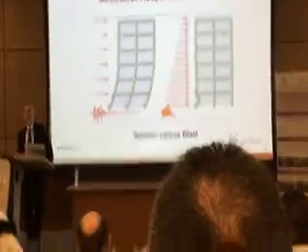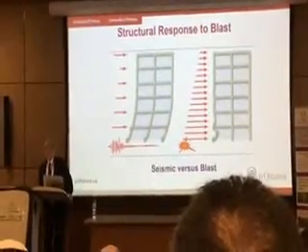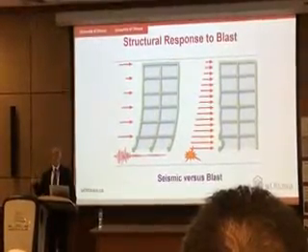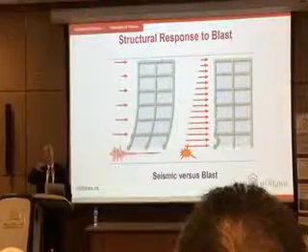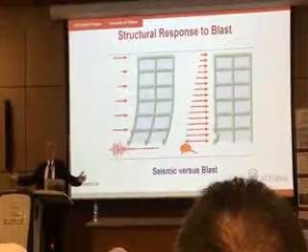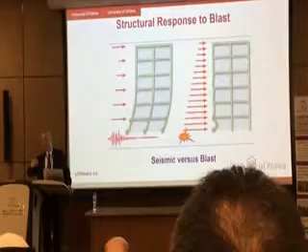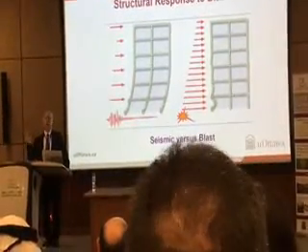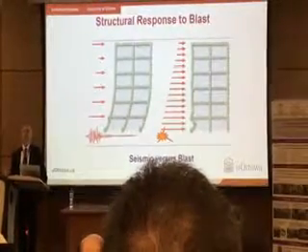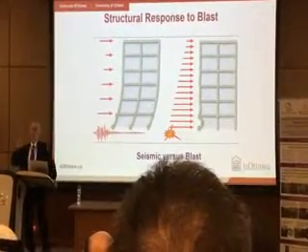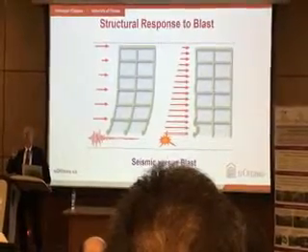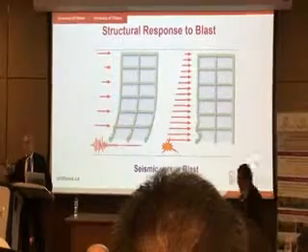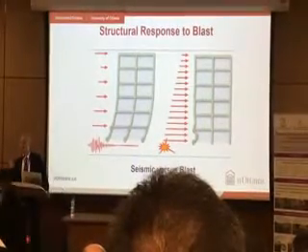In September of 2017, I was in Mexico again. There was another earthquake. This time, the former lake region survived, and then there was a transition zone between the hilly location and the former lake region, and this time 10-story buildings started falling apart because the earthquake frequency characteristics were such that the frequency of excitation was about 1 second, and 10-story buildings have a period of 1 second.